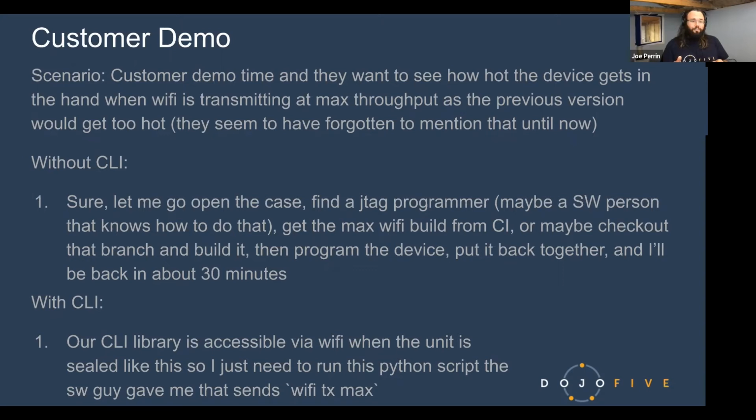And so I asked software guys, okay, give me something that just steps through the LED brightnesses. And they did. And so we showed that to them. They're like, great, we don't like that lowest one, but that second to lowest one is maybe too bright. Like, what's right in the middle? I'm like, well, I don't have a build that gives me right in the middle. So that was a call for another software build. Luckily, in the meantime, I had a constant current supply that I had wired up into a board with a potentiometer. So I was able to sweep the brightnesses and back calculate for the software guys later.